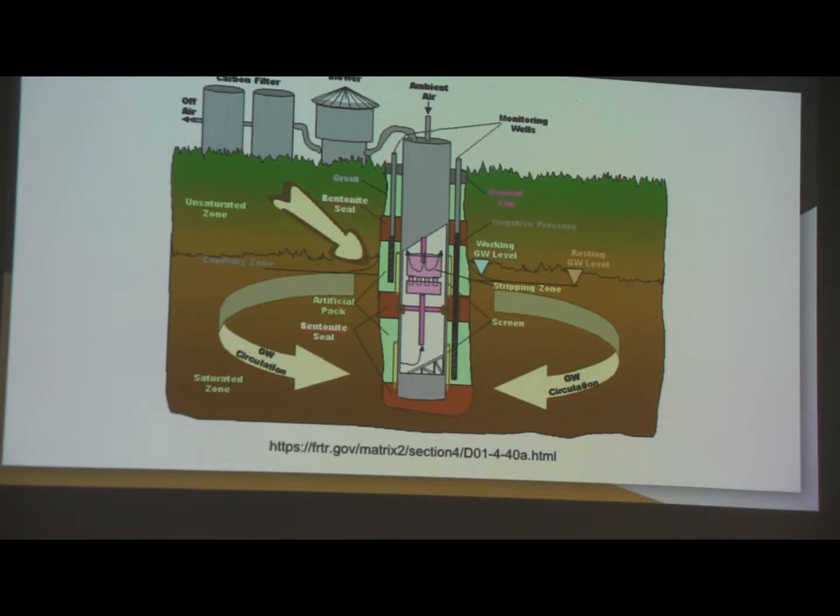So here's a picture of that in-well air stripping. Up here you have your upper screens, and down here are the lower screens. The pressurized air is going to come down and bring that water in up through the well. Right here, it's the W double arrows. That's where the VOCs are going to rise up to the top and then go to those packed columns. Here it's a blower and an activated carbon filter, but essentially this is the soil vapor extraction system. The water, while the VOCs go up, is going to be injected right back in, getting that circulating well effect.